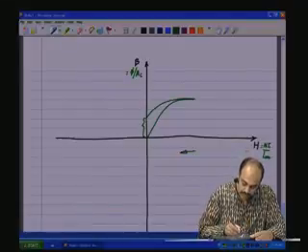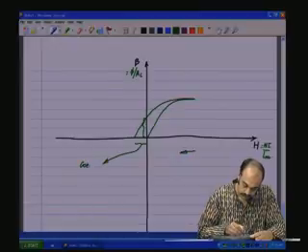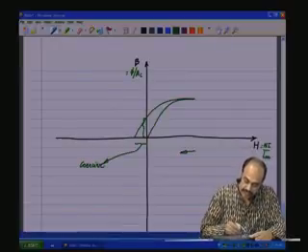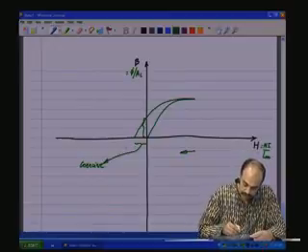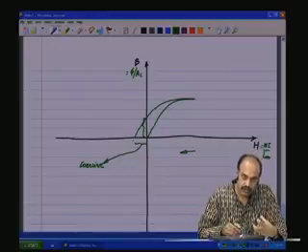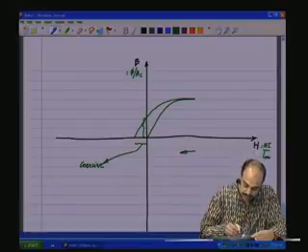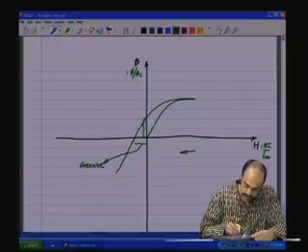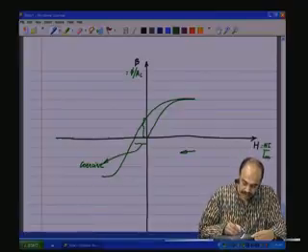To make that 0, you have to give a coercive force in the negative direction, that is, you have to give a negative field intensity or negative MMF in the other direction, then the flux is totally removed. So when you start giving H in the negative direction, this continues further, then beyond a particular value, flux does not go any further, it saturates.